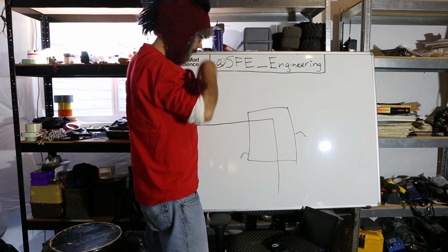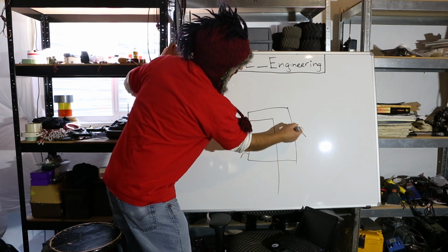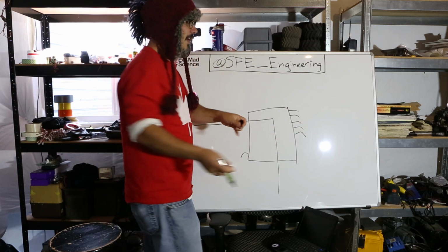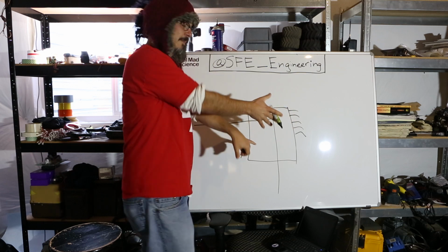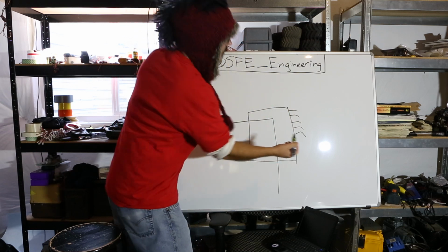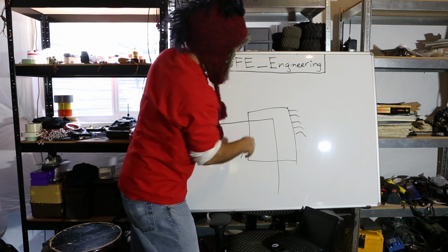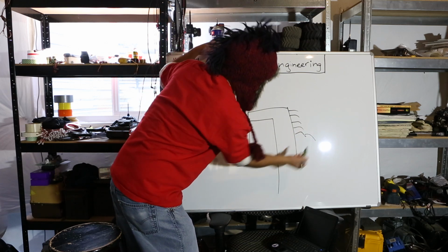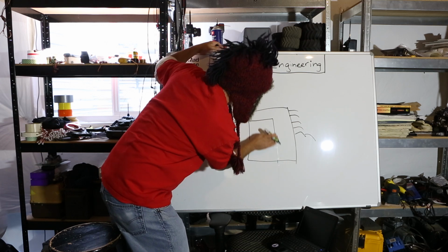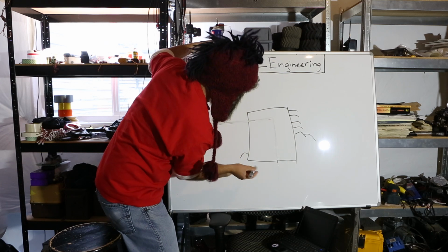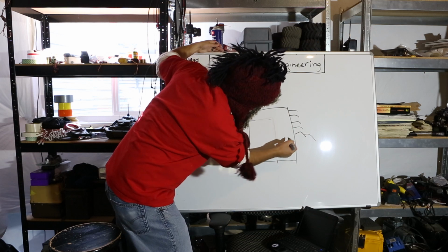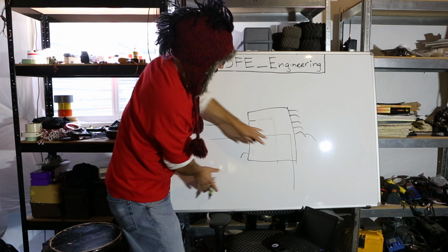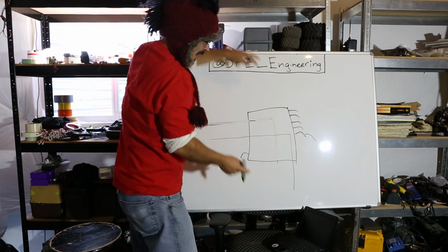So oftentimes what you want to do is find the sections, and again, if they've designed the chip well, these sections will be different internal to the part. And so the pins will reflect that, right? So you've got all your digital pins right over here. So maybe this one's the ground, so I might not put my analog plane there. I will put it right up underneath those parts, so my analog plane is taking up as much space underneath the chip as it can.